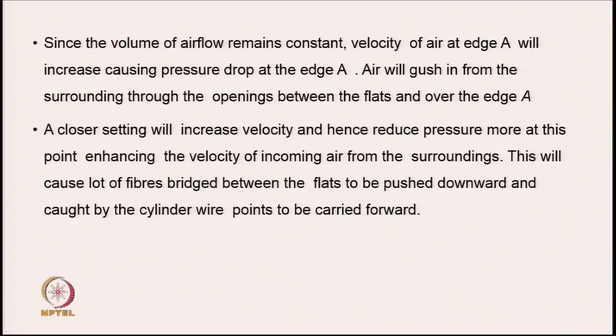A closer setting will increase the velocity and hence reduce the pressure more at this point, enhancing the velocity of incoming air from the surroundings. This will cause a lot of fibers breaching between the flats to be pushed downwards and caught by the cylinder wire points and will be carried forward.